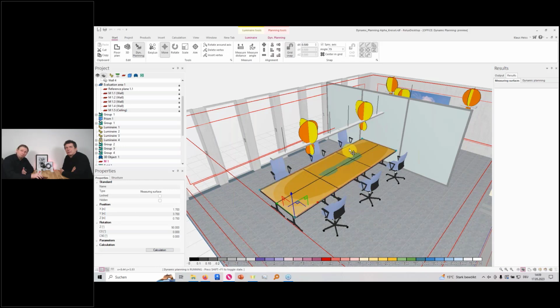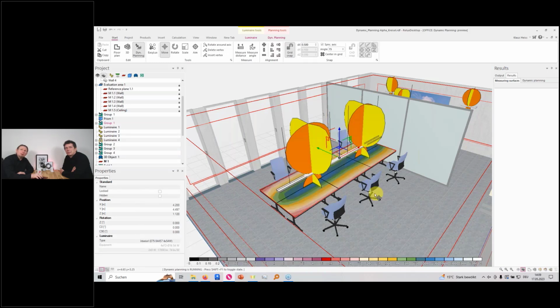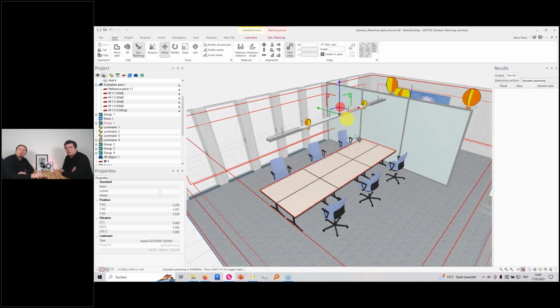And dynamic means if we change something, for example, if we change here the height of the luminaire to something else, we will need this 1 second of direct part calculation, and then we see another result, which is of course higher and less uniform. We should also see the values of it. We can see now we have a bad uniformity, but a brighter maximum of the illumination of the surface. And of course, if we do it vice versa, higher up, then we get a better uniformity, no surprise, but lower illumination levels. So this is the trick.